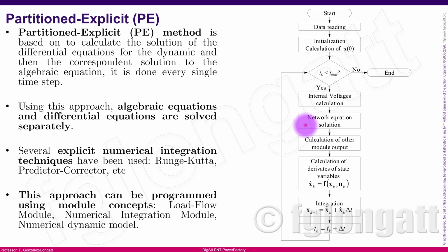What is the partition explicit? The partition explicit is the approach that is quite well applied for power system analysis. It's basically solving the differential equations and the algebraic equations in a separate way, okay? What you are doing is solving first the differential equation, then with the solution of the differential equation you go and solve the algebraic equations, and you keep doing this until you reach the whole simulation time, okay?